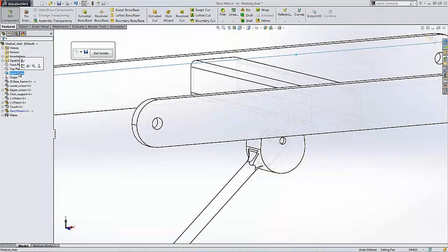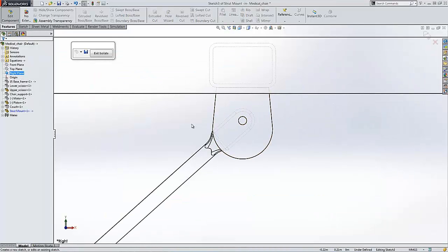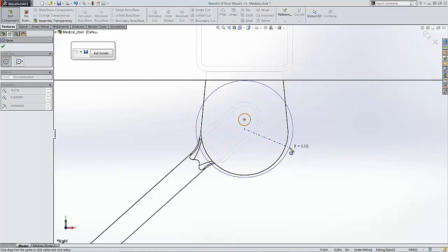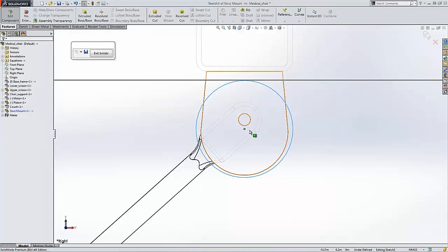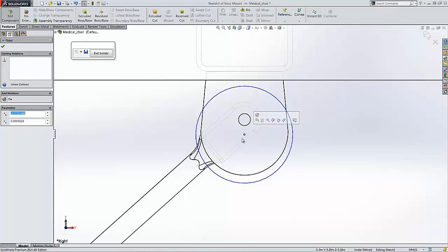So let's create the shape using the gesture wheel, and as for selecting a cut extrude, well, we're going to use the S shortcut key. Now your S shortcut key is context sensitive too, so if you press it while sketching, it's going to provide sketch tools. Out with the sketch, we'll get features like our cut extrude. So I'll show you that in just a moment here.